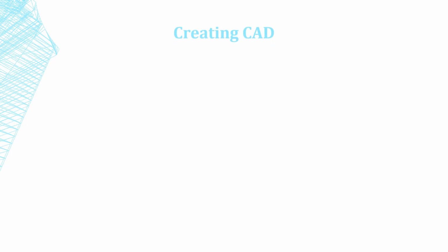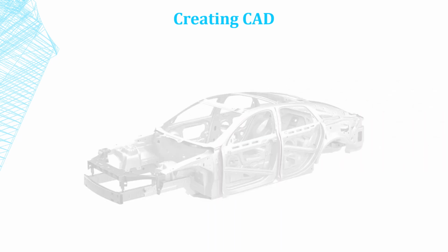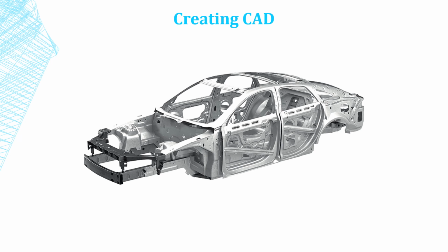First step of FE modeling is to create the CAD. The creation of CAD depends on the type of geometry. If geometry has cross-sections along its length and the length is large, then we can create line bodies only and assign different cross-sections to them. Examples are beams, rods, shafts. If geometry has sheets or plates with small thickness, then we can create surface bodies and assign the thicknesses to them. Examples are BIW parts, sheet panels.